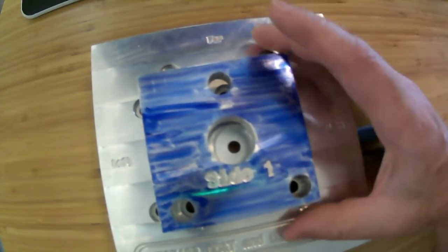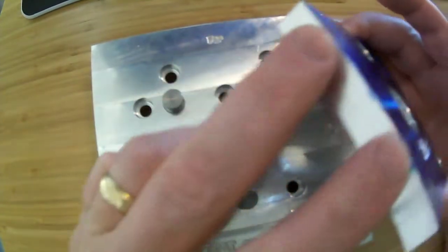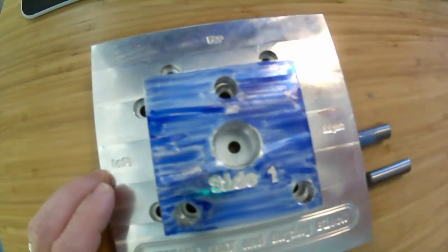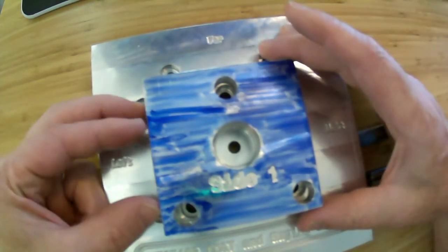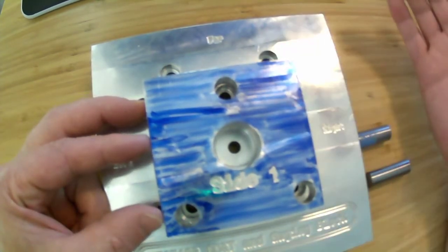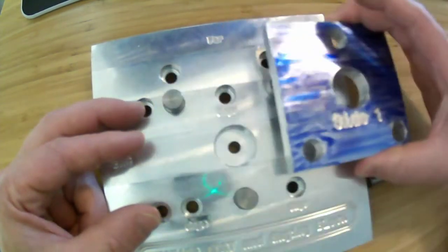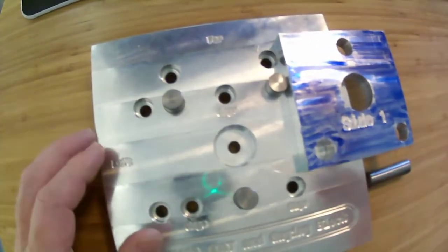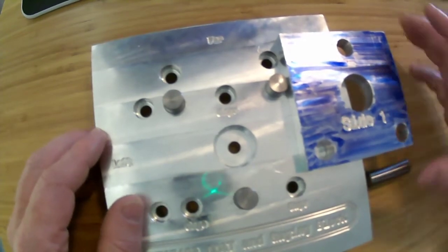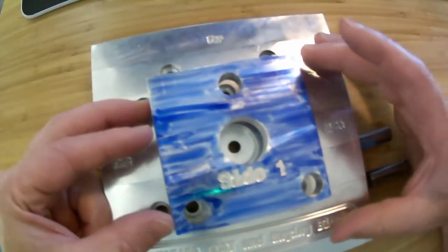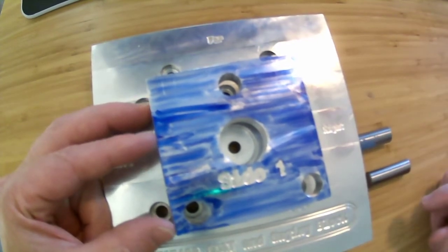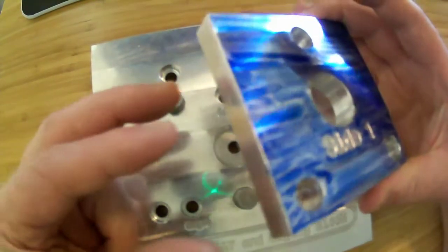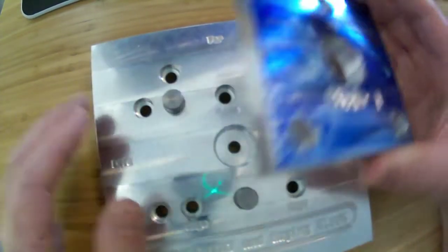If we just said that 3 points defines a plane and we want to position this plane here on the side, why do we not use 3 points on the side? If we want to position a plane, we would use 3 points, right? Well, the problem is if we're assuming that this base and this part are completely rigid, and that they are not perfect surfaces, then if I were to try to touch this in 3 locations on the side, either the part would not be able to touch these 3 locations, or it would not be able to touch these 3 locations.